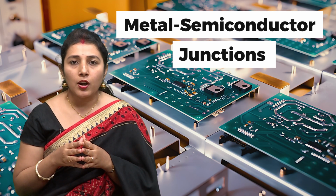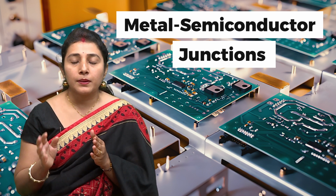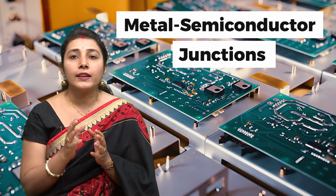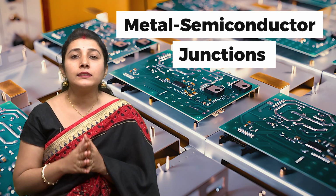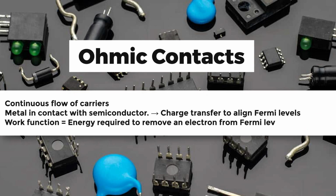Thus, to form an ohmic contact, the majority carriers of the semiconductor connected with the metal must align at the metal-semiconductor junction. When the majority carriers align with the metal-semiconductor junction, an ohmic contact is formed and the characteristics are almost linear. So in the case of an ohmic contact, there is a continuous flow of charges. When metal is in contact with the semiconductor, charge transfer causes alignment of the Fermi energy level. Hence, we can define work function as the energy required to remove an electron from the Fermi energy level to vacuum.